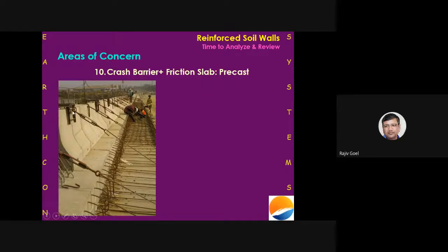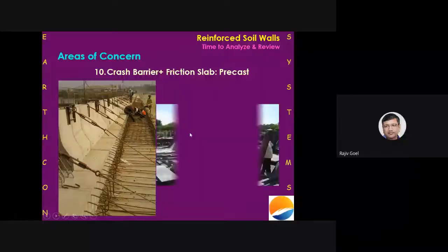And this is the problem solution. The solution to the problem I was telling you about, that we are putting these turnbuckles here so that this precast piece is not transferring any load to the panel below. If I don't use these turnbuckles, this piece is not stable by itself, and it would go and rest on the panel below. So as long as I'm using these turnbuckles, I am not allowing it to rest on the panel below.